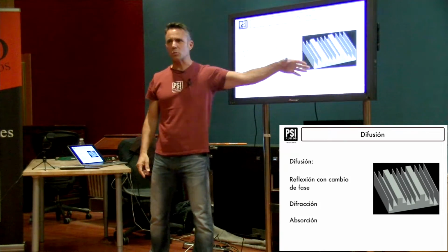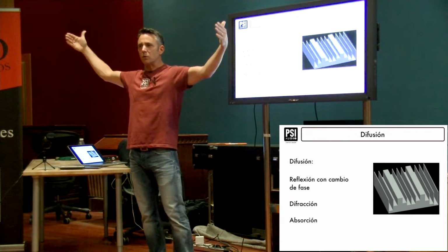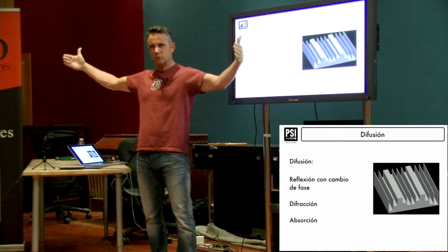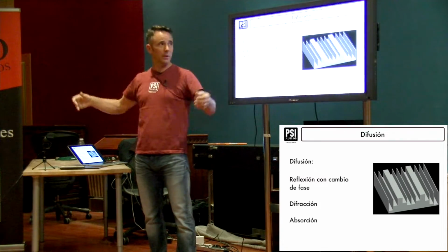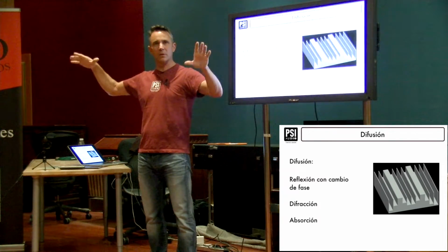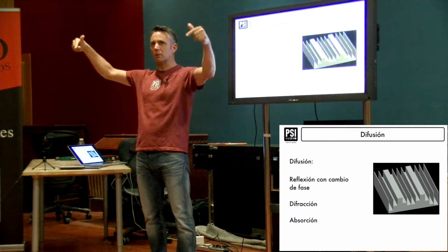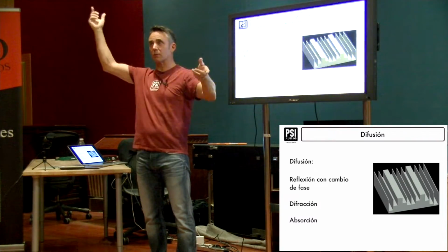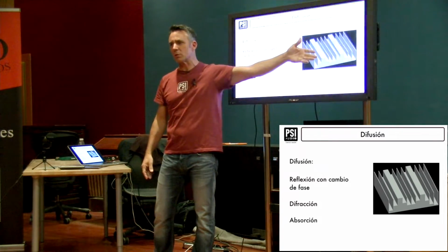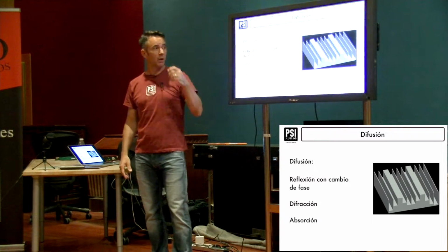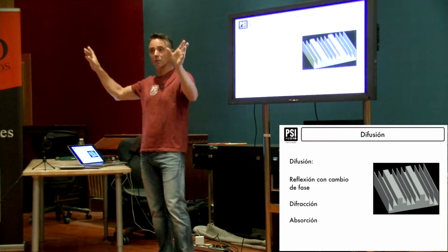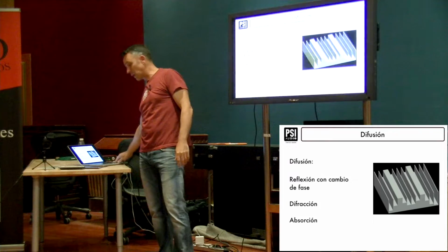Diffusion works very well when you have, for example, relatively high frequencies, and at first reflection points it works very well. And then you can have different angles, and instead of all the sound coming at the same place, some of it is going in different directions. That's diffusion, and there are a lot of diffusers on the market that all work very well, and you can also use books and things like that in a bookshelf that also have some effect.